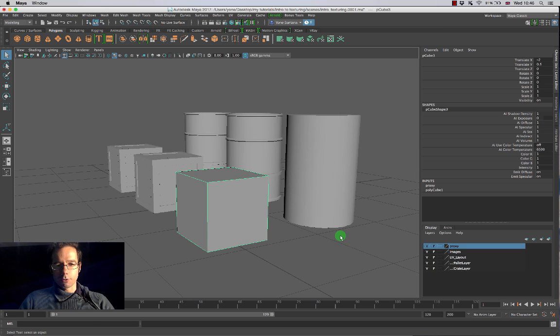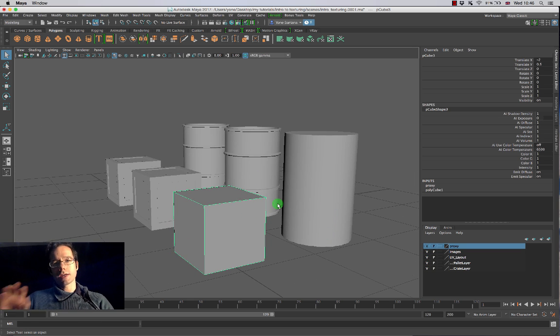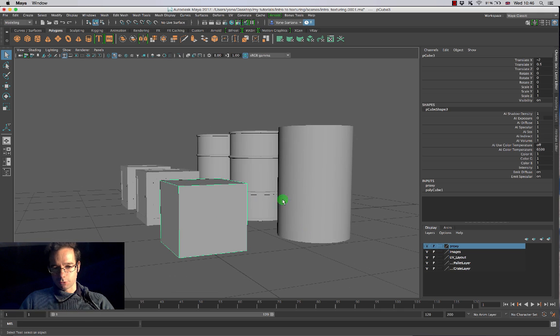One thing I always like to point out to people is that 3D layers are not the same as Photoshop layers. If I've got these proxy objects over here and I move them up and down in my layer stack by using these arrows, you're going to see that it's not like in Photoshop, where the layers move what's occluded forwards and backwards. It's not exactly the same as grouping, and I would hesitate to call them a group. It's more like a little collection of objects.